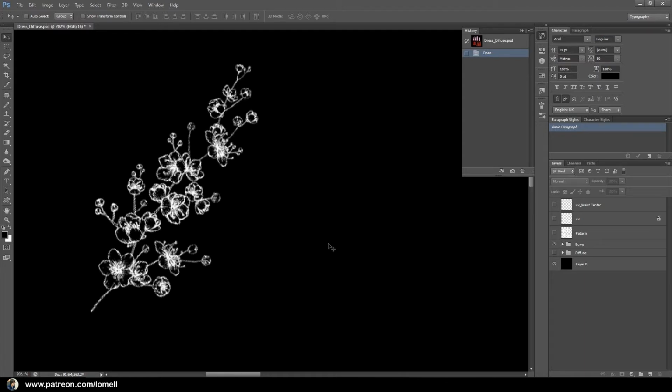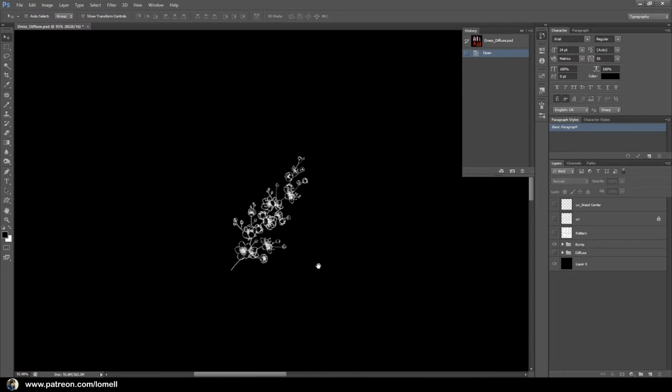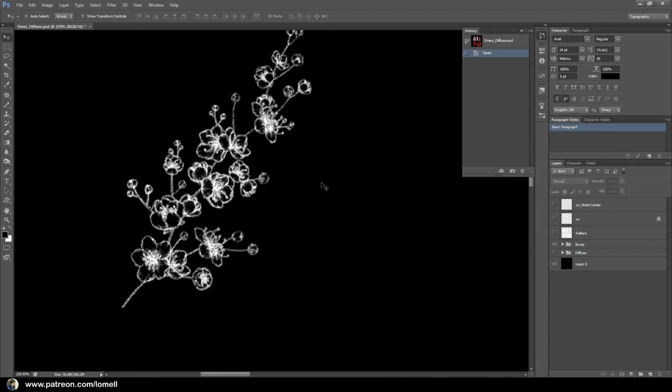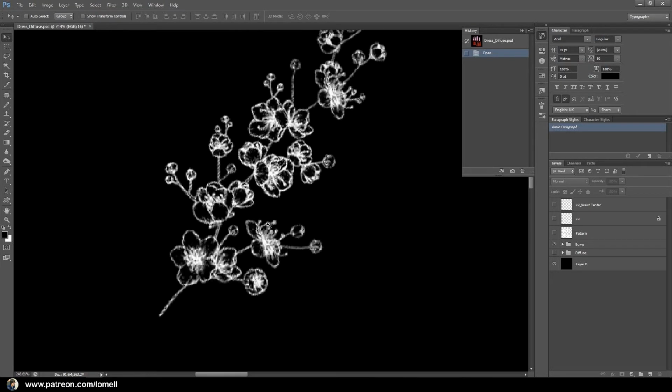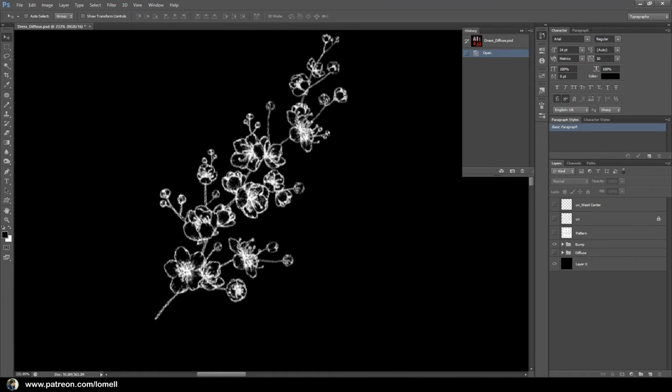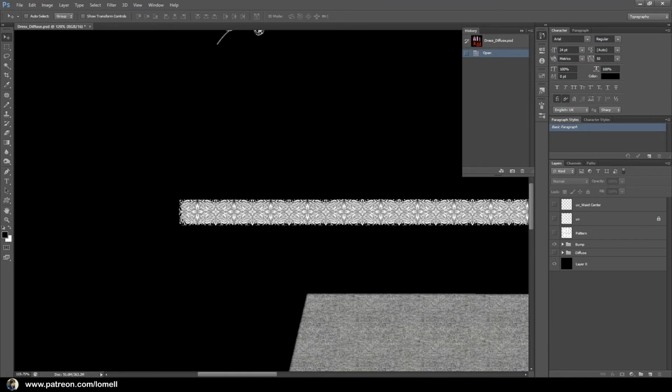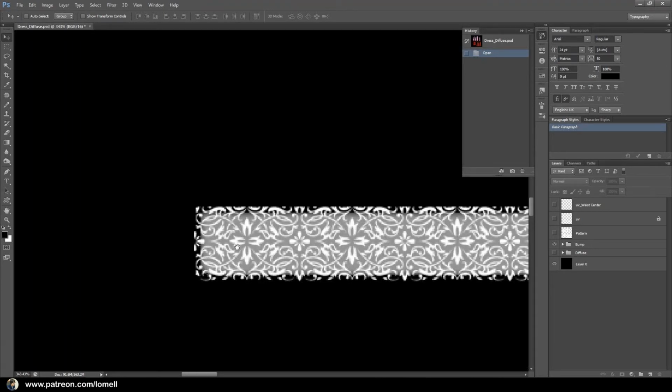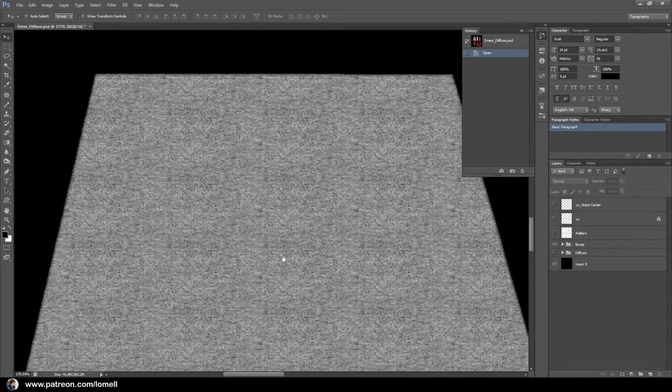If you apply this bump map to our object, the dark area would keep the surface totally flat, while the white part would give such a bump effect onto our surface. And as you can see here, a middle gray color is gonna lift up the surface just at the middle between the dark and the white color.